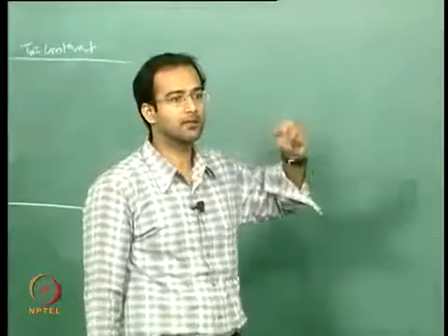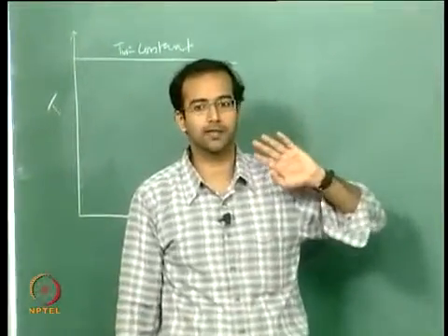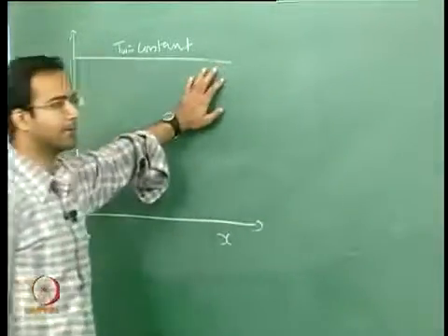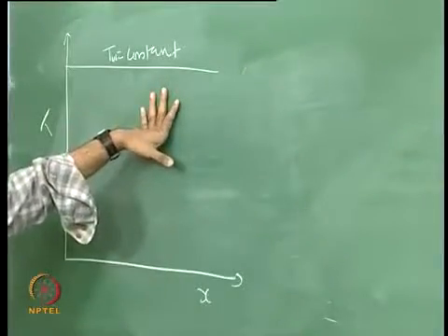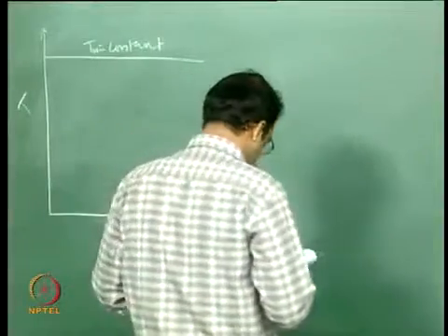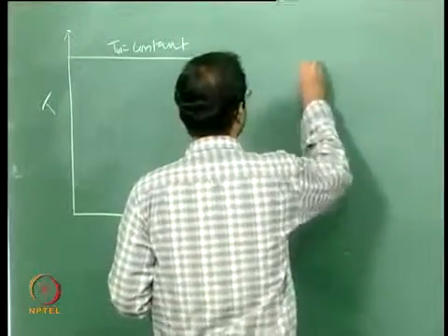There, from Newton's law of cooling you directly showed that the slopes have to be the same, but here it is not true. So in this case the wall temperature is of course a constant, but how the local temperature and the mean temperature vary is not clear. So to determine the variation, what we will do is just take a simple energy balance. So you take a duct,